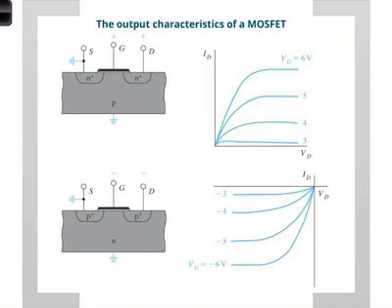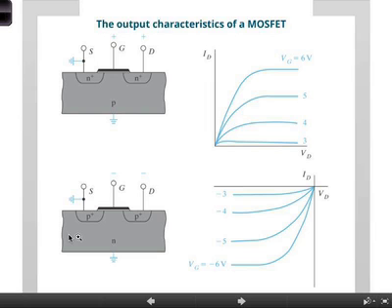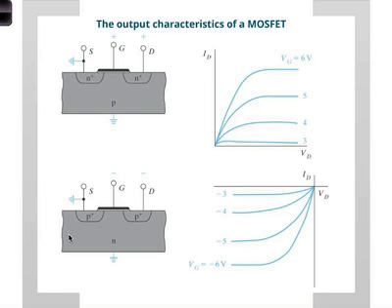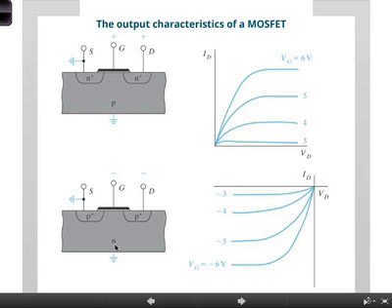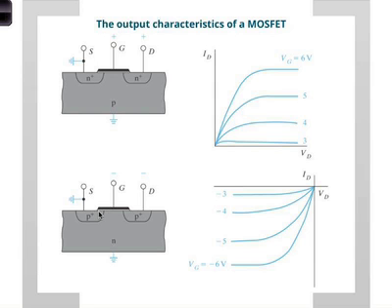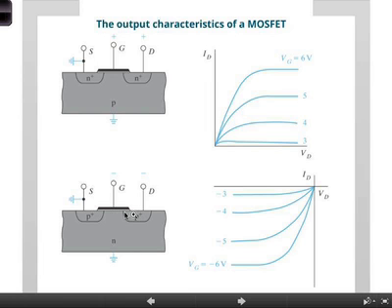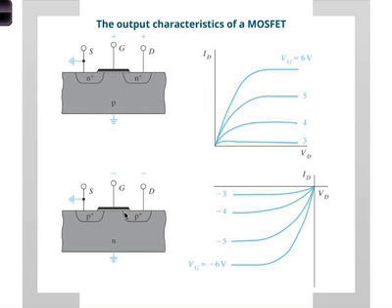Okay, so let's think about the output characteristics of the MOSFET. For the N-channel MOSFET we just saw, the curves look like that. For the P-channel MOSFET, let's think about this for a second. Because they're inverted, but we need to understand why they're inverted. First of all, for the P-channel MOSFET, it's an N-type substrate, and you have to apply a negative voltage to create the channel. Right? You have to pull the holes in, you have to make it locally P-type at that interface. So you need to create a P-type channel. So obviously the gate has to be negative.